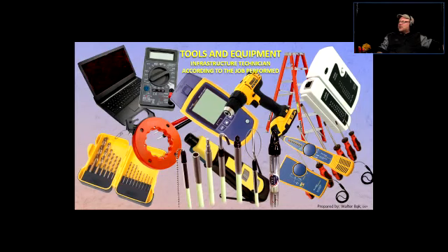So the metallic ones are good for the most part, but if you are going to add more wires into a conduit that already has some existing wires, then you might want to use a fiberglass one, because it's gentler on things. Shoving in the metallic fish might actually damage the existing wires. That's one. Two, quite often you're going to have to use some lubricants, and you're going to have to lubricate that fish periodically when you put that in, so it can actually go and weave itself around the other wires. If you don't, you can actually damage the existing wires that are inside the pipe.